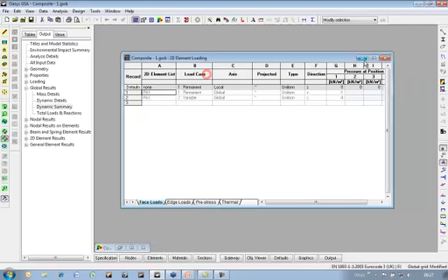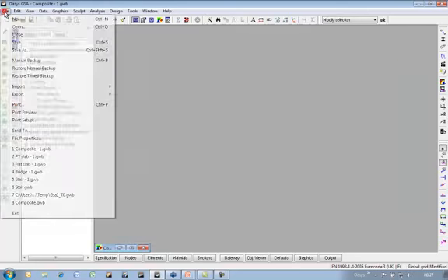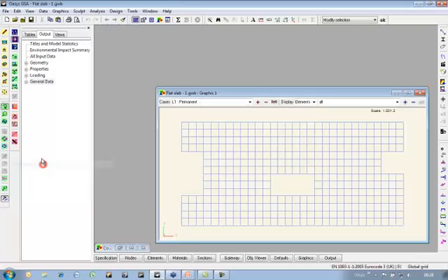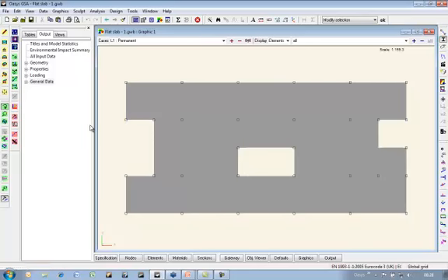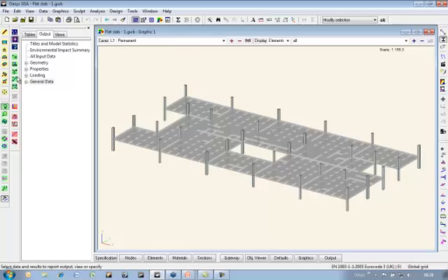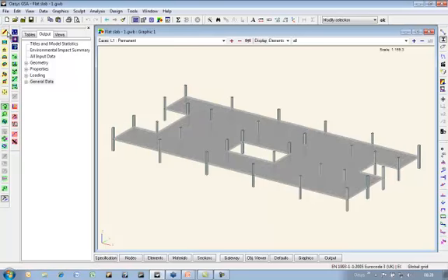What we also could do is call up a similar flat slab model. Now this is exactly the same geometry, but with a flat slab instead. Now with a flat slab, with the concrete, the stiffness very much depends on the reinforcement in the slab as well.